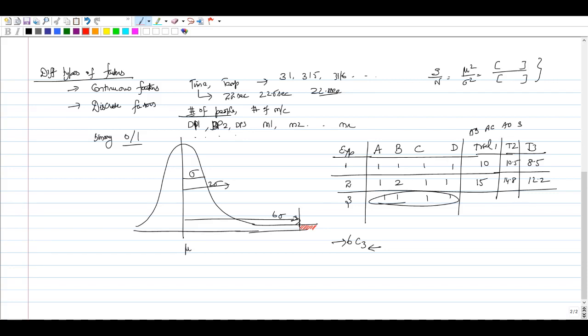And what I'm going to shade in red, I'm just drawing the right part of it. But you can imagine that this is symmetric, so there is a red region on the other side also. Now what we are trying to mean here is, this region that I marked in red should be 3.4 parts per million, meaning 3.4 divided by 10 raised to 6. That should be the quantity.